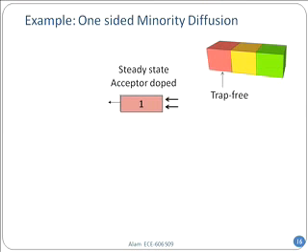Now let's think about the first region. You see what is going to happen: in the yellow part, light will come in and generate electron-hole pairs, and they are going to get out through the red side and through the green side. They are trying to get out of the device because there are too many carriers. So by diffusion, they will try to get out of the device. So let's think about that. Again, acceptor dropped, so we know that. Let's see whether we can solve it. Again, the full equation.